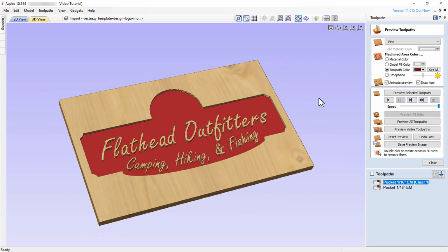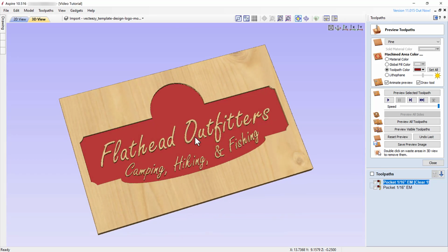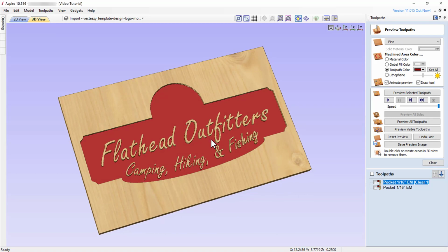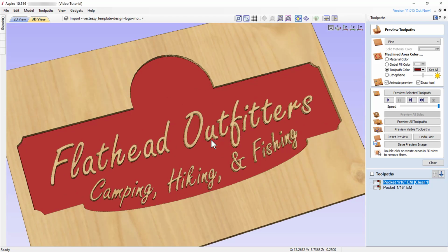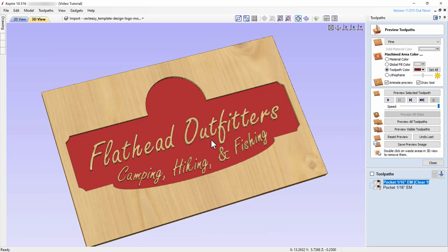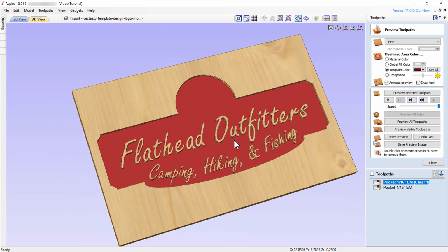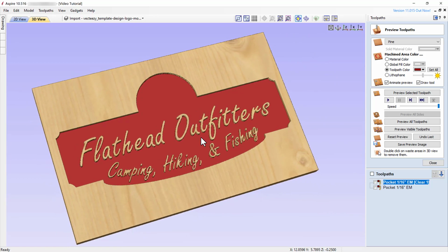A more versatile method of viewing our project is to hold down the left mouse button while moving the mouse. Go ahead and try that on your own to see what I mean. You can also use the scroll wheel to enlarge or shrink the project. By clicking and holding both the left and right mouse buttons down at the same time, we can move our project to a different location on the canvas.